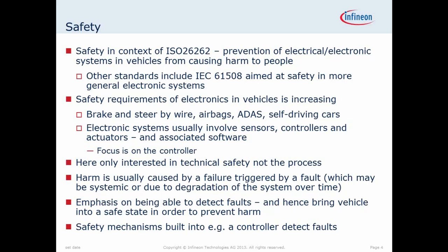Going back to the notion of harm I introduced in the first sentence: harm is usually caused by a failure, and that failure is usually triggered by a fault. These are technical terms. A fault may be systemic, as Sergio said, or it may be due to something like the degradation of your system over time, or it may be due to some transient happening like an alpha particle strike.